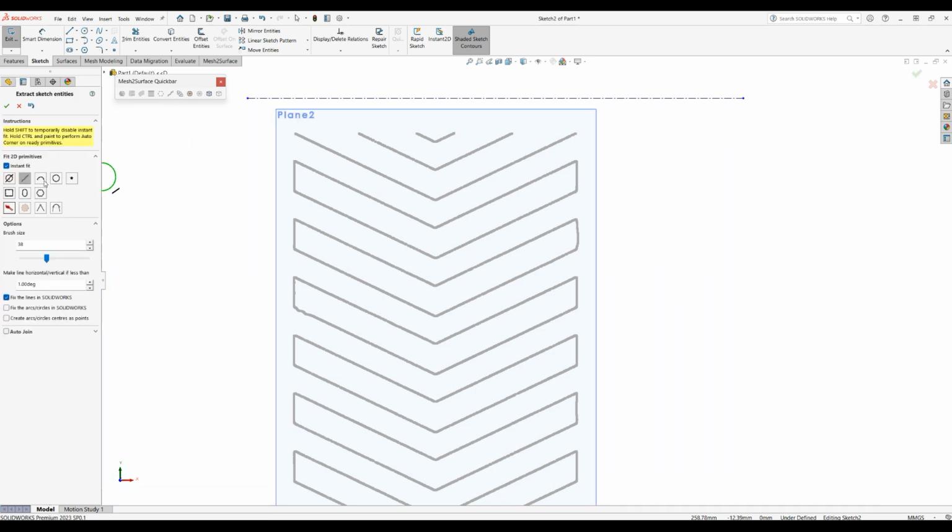We'll make sure that I have pre-selected the line, and then I simply hold my left mouse button down so the software can extract this information from the underlying scan data. For the purposes of demonstration, I will just extract several, so you can get the different angles and probably get the average out of them.